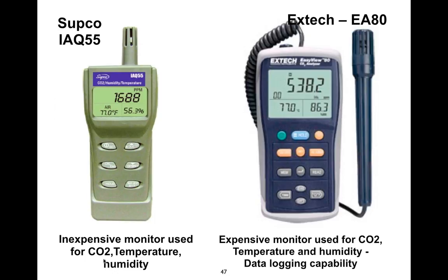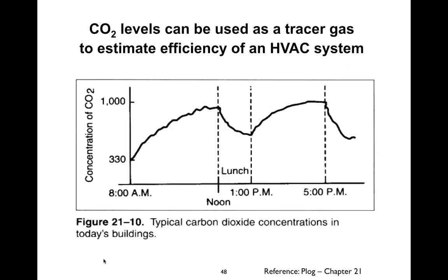Okay, you can also use electronic devices for measuring outside air. These are two examples of these monitors. Typically, in addition to measuring CO2 levels, they'll also test for carbon monoxide, temperature, and humidity at the same time, so you get a bit more information out of it. And the one on the right, as well as a couple we have at school, will data log. Over time, you can get it to take a reading every minute, leave it behind, and then print out a graph of what the CO2 levels were over a period of time.